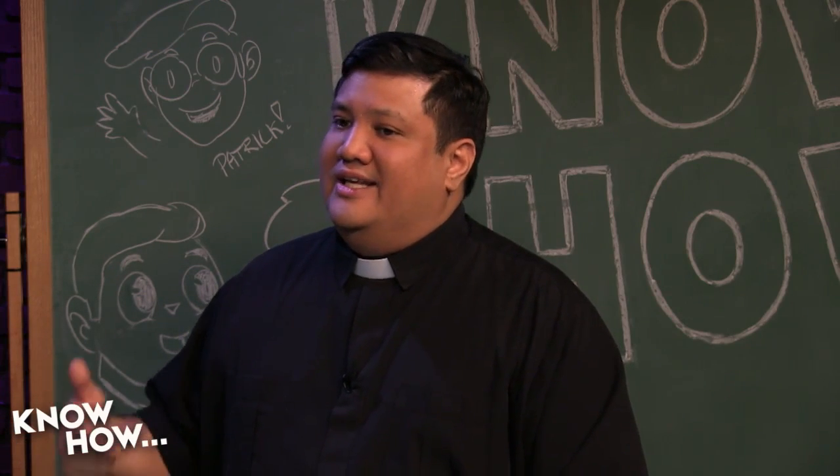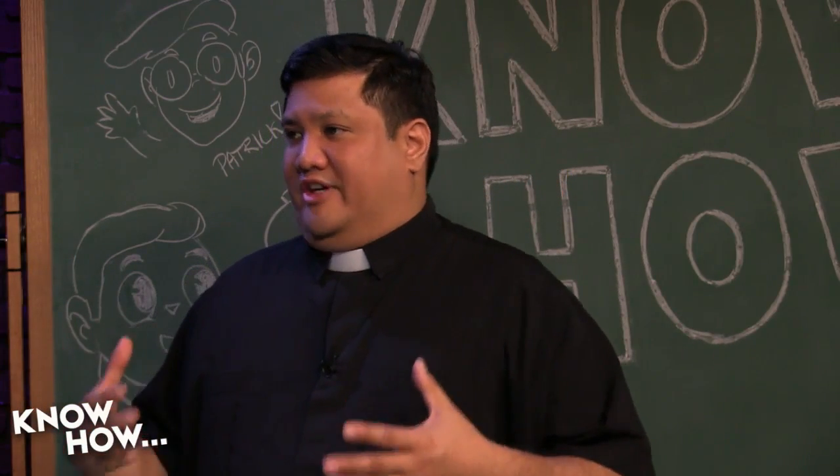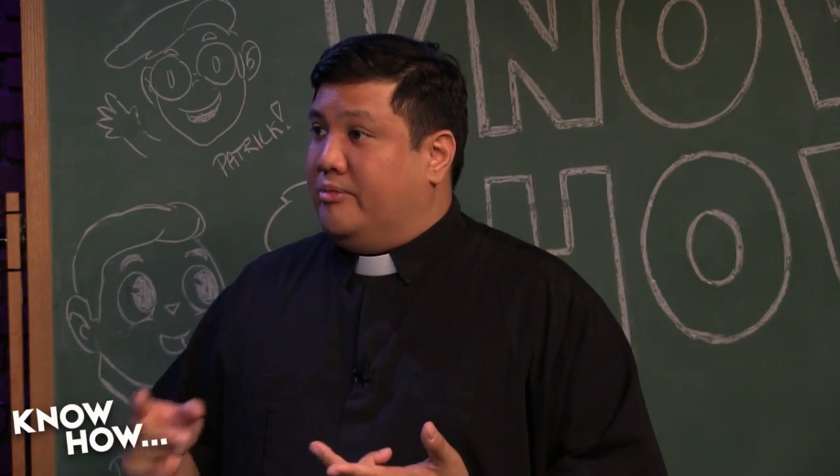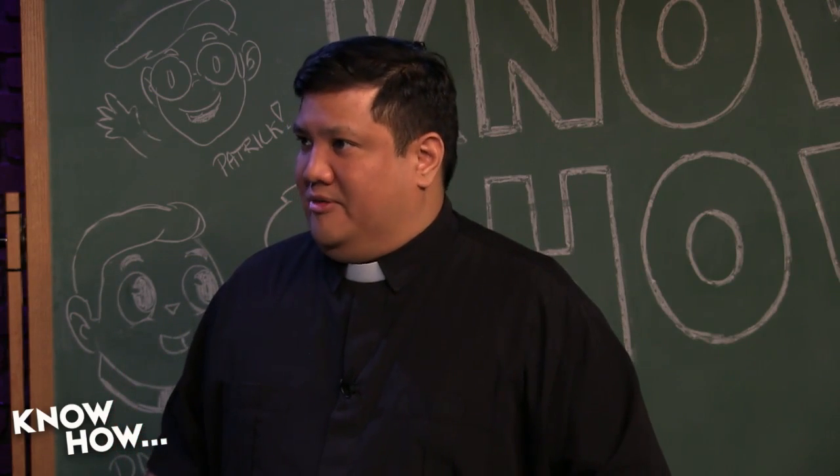We want our system memory to be fast, but because it's volatile, if I'm not refreshing the cells every so often, they just deteriorate into nothing. Which is why that goes away when it loses power. Those are the two types of memory that most of us play with. We play with flash because that's where we upload our programs to, and we play with the SRAM because anytime a program is running, it's using the system memory, correct?